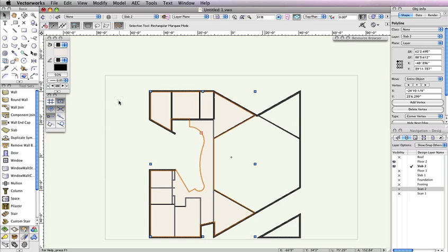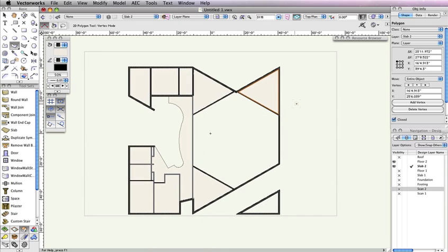So again, enable the Polygon tool in the Basic tool palette, and follow the vertex points set in this video, and set these same points in your file. Just like last time, don't forget to double-click to complete the polygon. The last portion of the slab you need to create is in the bottom right corner. It's also the easiest to create.